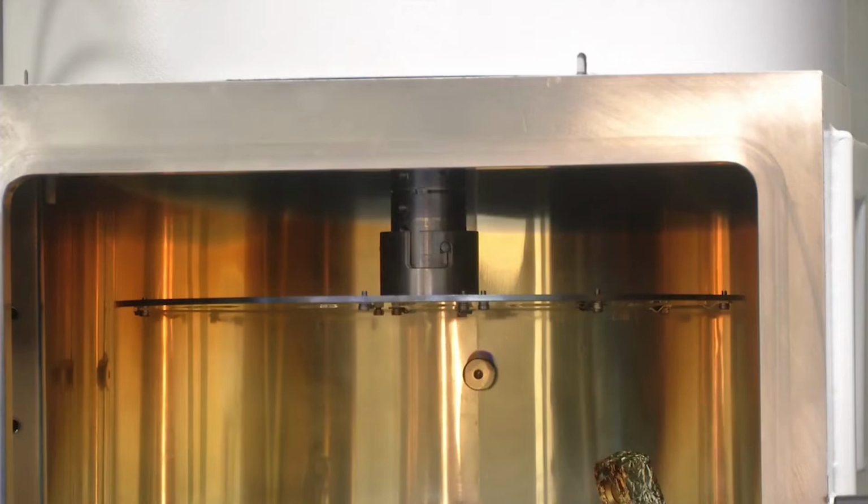If we do not rotate the substrate, then the electron beam evaporated metal will not fall uniformly on all the wafers. To make it fall uniformly on all the wafers, we can control the rotation of the chuck and hence obtain a very uniform layer for all the 5 substrates or any number of substrates.